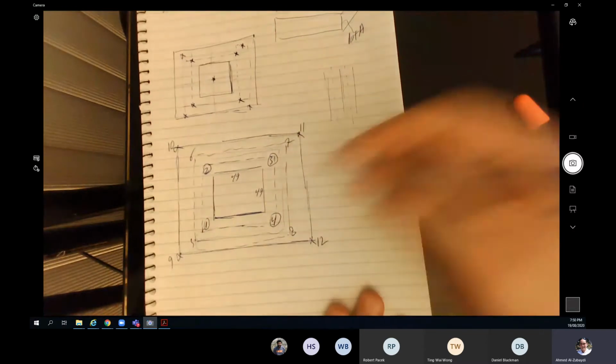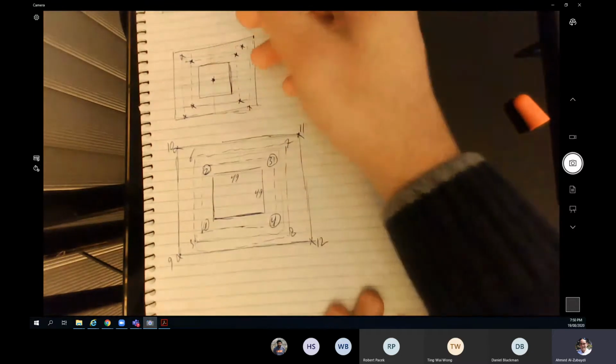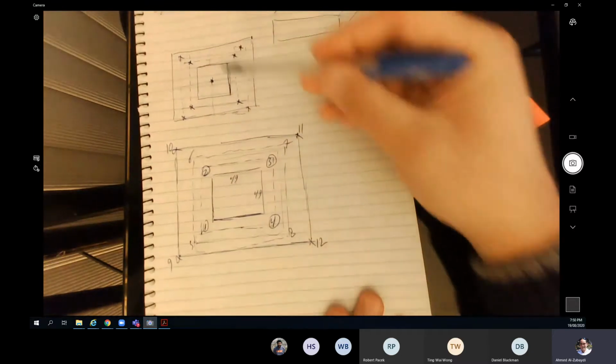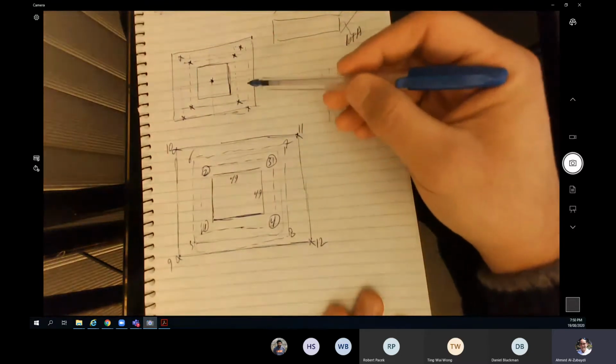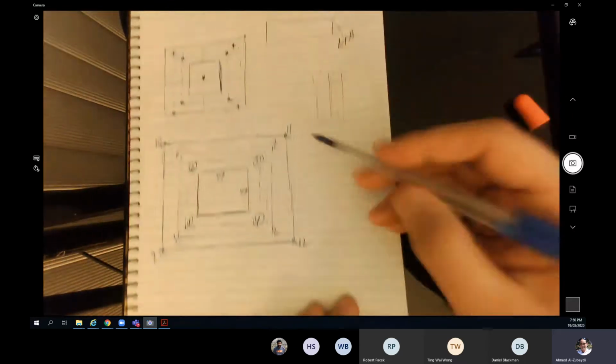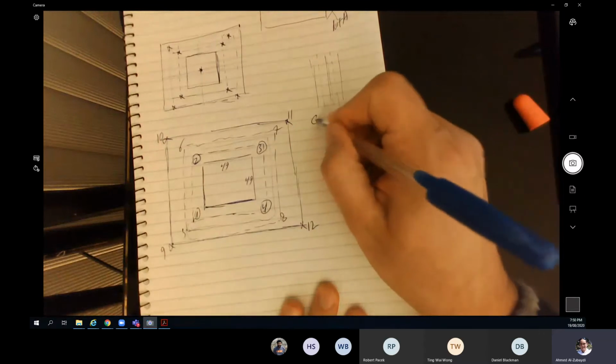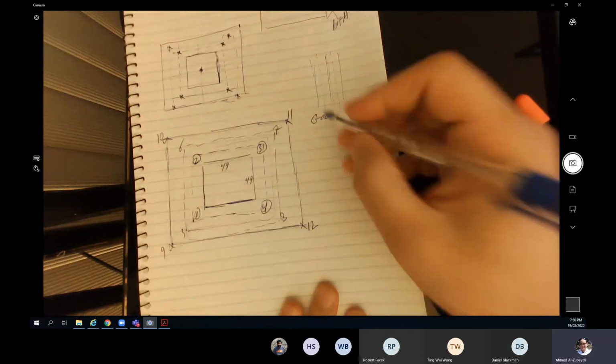So simply, we're going to write down the G code. And of course, you have to mention here: profile cutting around the square in the middle using the cutting tool with the diameter of 12 millimeter. That's the description of the operation. The G code, I can simplify that for you. G00 to the point number 1.